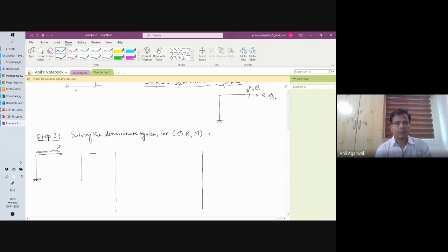So bending moment diagram is not something too difficult to do here. I'll just create a gap here between the two members. There is a vertical member here, there is a horizontal member here. Now, if it's a horizontal member only and this W load is acting, and the only support you have is at this end, where you are getting the entire fixity, what would this horizontal member be behaving like? You have a horizontal member projecting out. It is a very simple system. What is that system? Cantilever. Exactly. So you already know the bending moment diagram for a cantilever, right?